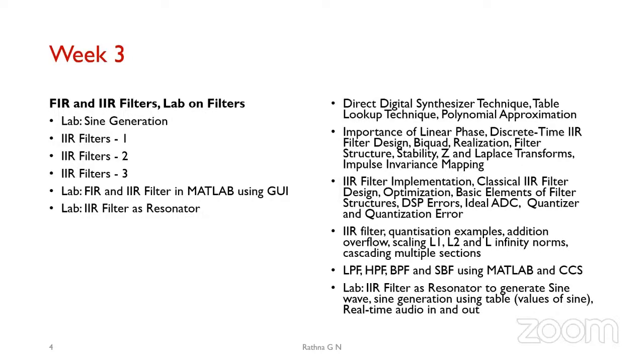And then we have to use the Z transform here basically, which is derived from the Laplace transform. One important thing to keep in mind when designing your IIR filters is that it is not a linear phase. The phase is going to be different for different frequencies in the same signal, whereas it is constant in an FIR filter.